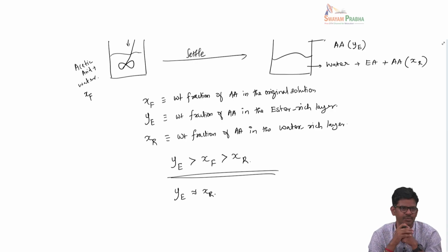That is a choice we have to make, unlike in distillation where the vapor phase is created from the liquid phase itself, where we do not have much of a choice in changing the chemical nature of the gas. But here in liquid-liquid extraction, like in absorption and desorption, we add a new phase, and we have a choice to choose that phase, such that the solute can be distributed in larger quantities. So, selection of a solvent for liquid-liquid extraction is one big decision making process.